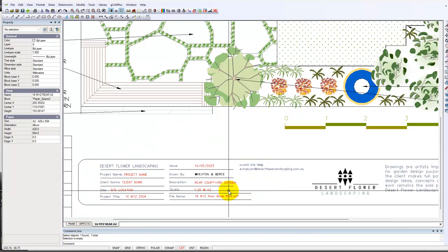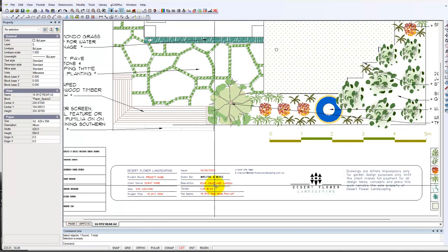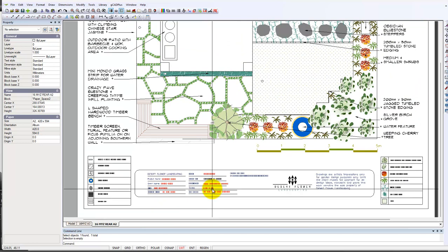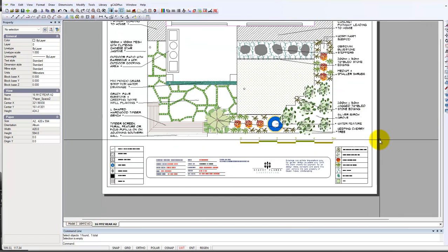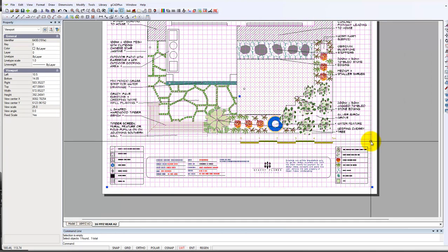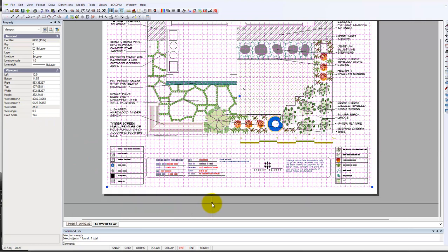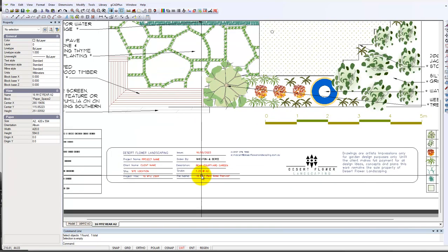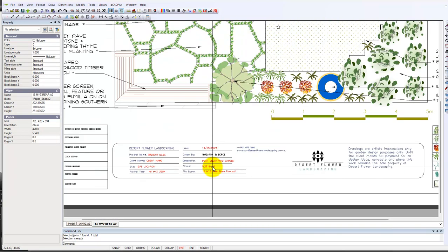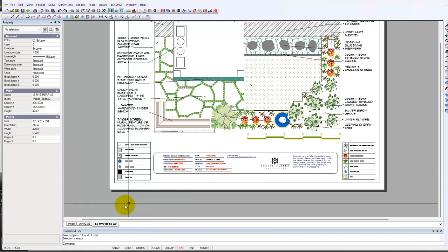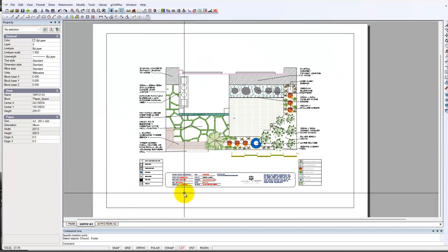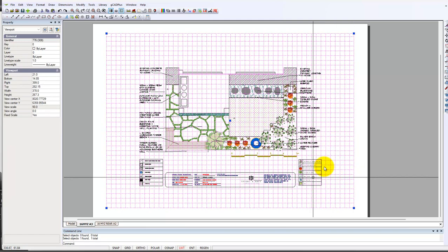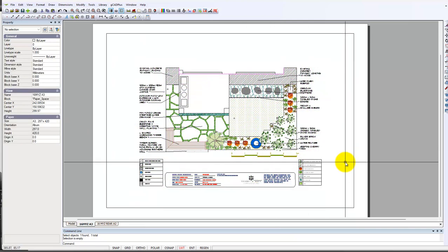Now, we've made in that title block the text red, and we have one block at the moment, but if we pick our layout sheet, notice it's 1 to 25, we need to update that information. And if we zoom in here, it's 1 to 25 on A2, which is correct. But if we go to our A3 sheet, I wasn't responsible for doing this, but it's set at 1 to 50 at a fixed scale on that A3 sheet.